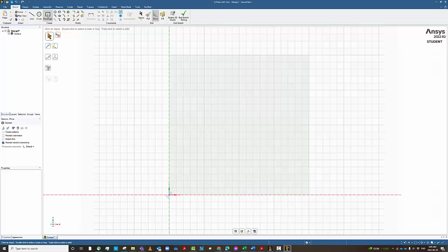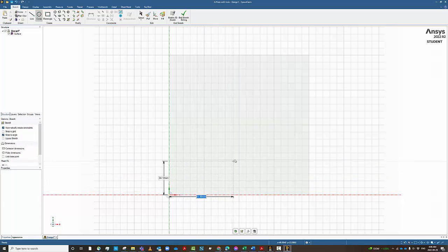We want to create a circle. So here you can click on circle, and then of course you start by clicking the center. You see here, it snaps to a grid to create the center. One other thing, if you bring your cursor here and you click on the shift key, it's going to allow you to locate where your circle is, right? So I can move to 50-50, which is this one here, okay? And basically you can select this as the center.